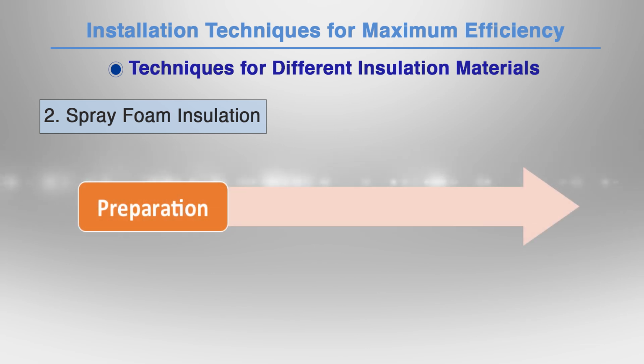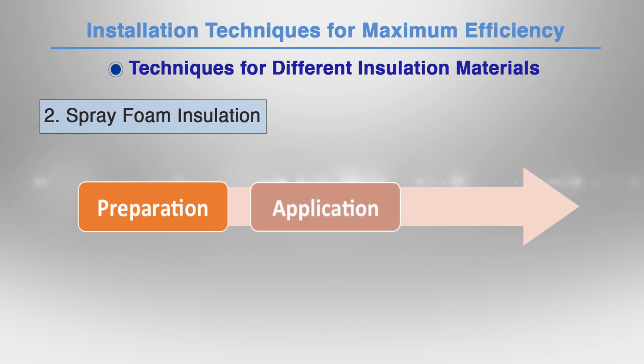Preparation of spray foam insulation: clean the area of dust, debris and moisture before applying spray foam. Ensure proper ventilation and wear protective gear. Application: apply spray foam in layers, allowing each layer to expand and cure before applying the next. This ensures even coverage and avoids excessive expansion.